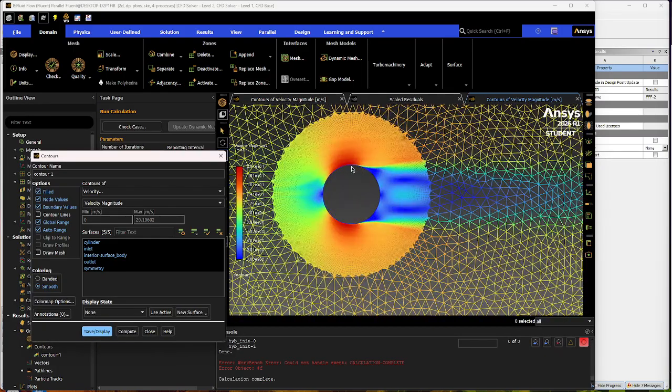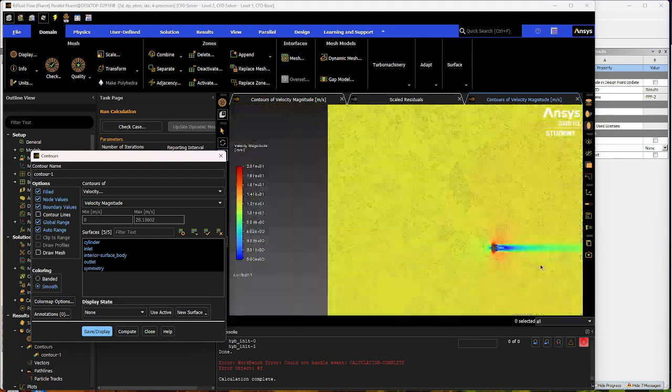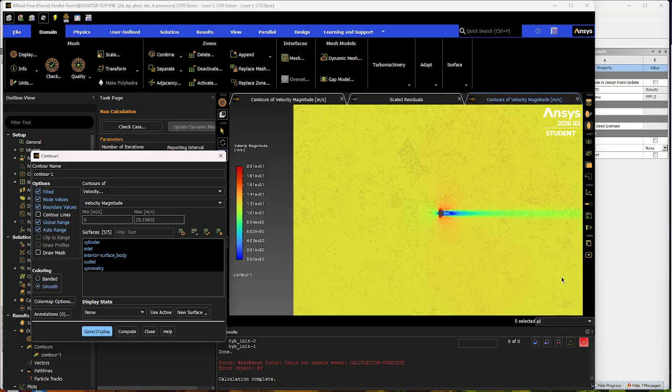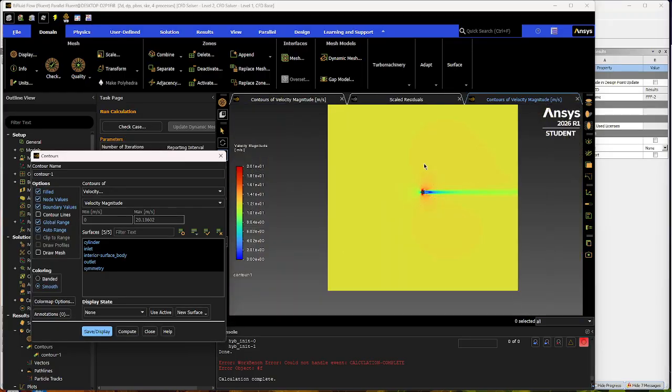So you have a lower angle of separation, so it separates later. It has a harder time separating because the turbulence is energizing the flow, and that helps the molecules grab hold of the cylinder for longer before they split off.